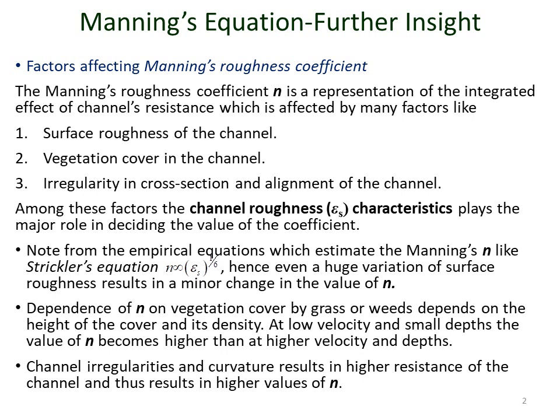Like Strickler's equation, remember in Strickler's equation, Manning's n was proportional to the surface roughness raised to the power 1/6. So in the empirical equation, n is proportional to some representative value of the surface roughness, let's say D50 or D90, raised to the power 1/6.